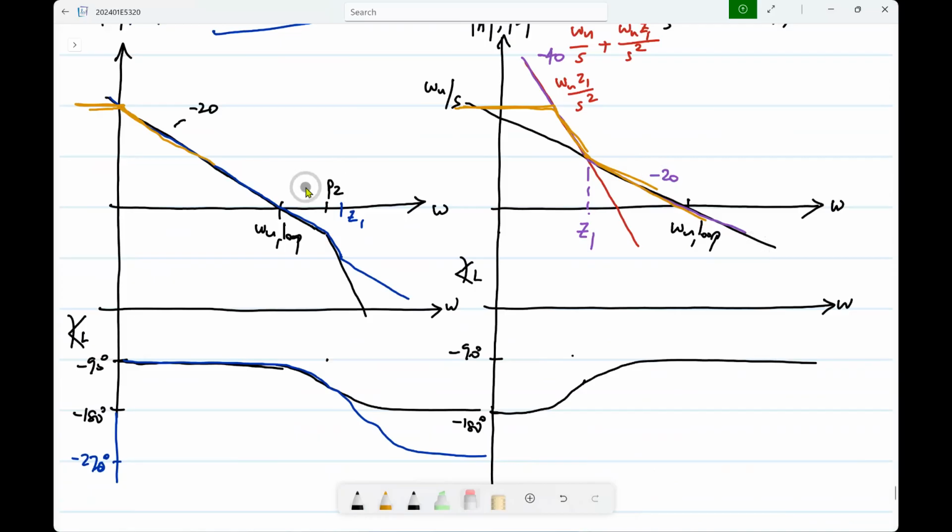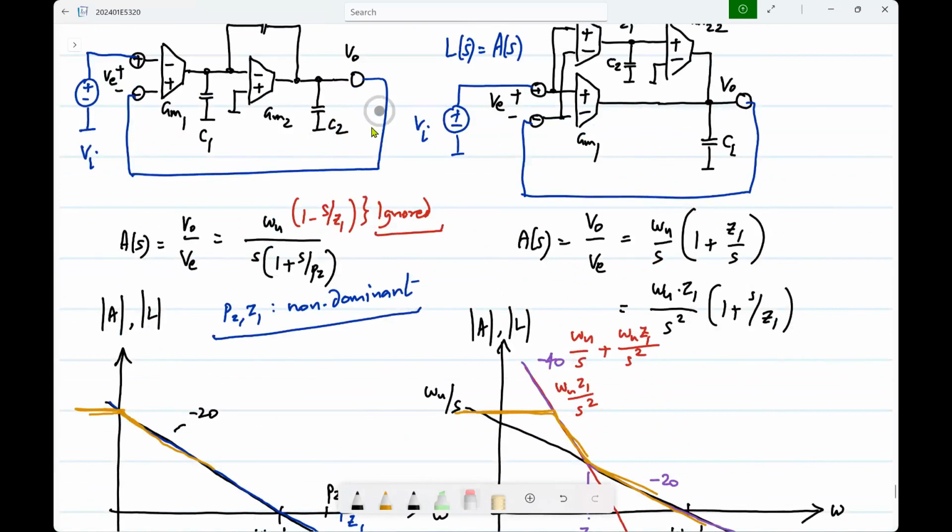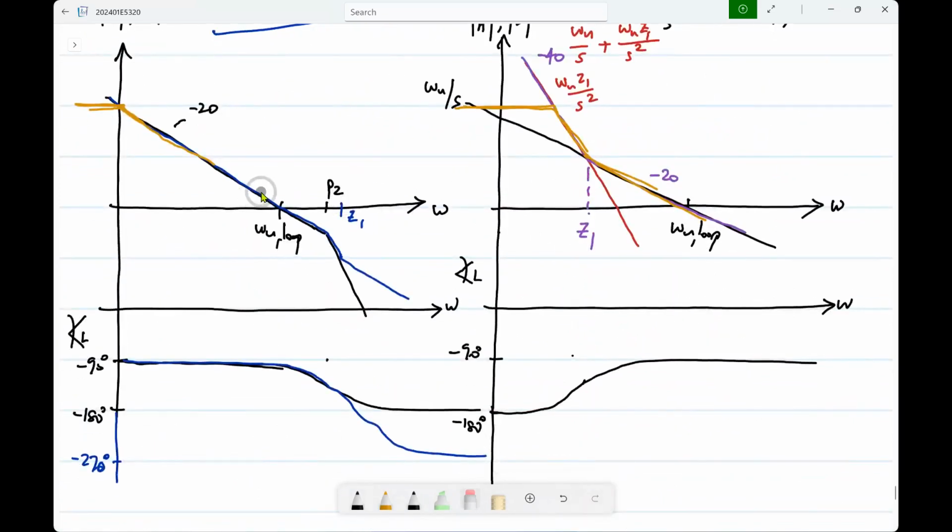So again, we will continue this, but this is the op-amp's transfer function, and it is also the loop gain if you have it in unity feedback. If you have, let's say, a non-inverting amplifier of gain K, what will be the loop gain with the same op-amp? I mean, what happens to these loop gain curves? What happens? Move? Where? Sideways, upwards, downwards? It will move down by a factor of K. So what happens to the stability margin on the left one if it moves down by a factor of K? It improves or remains the same if it's already good enough.